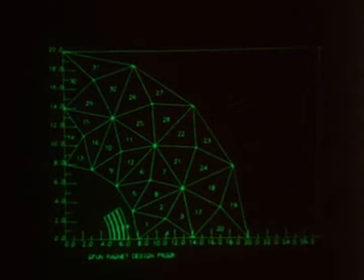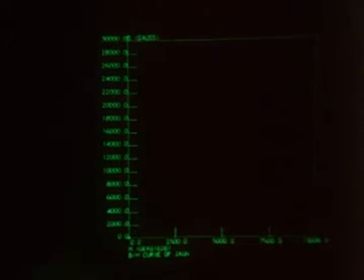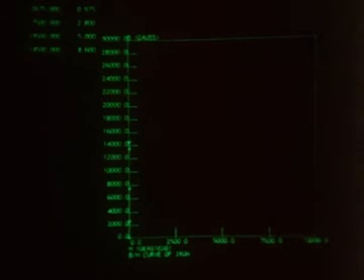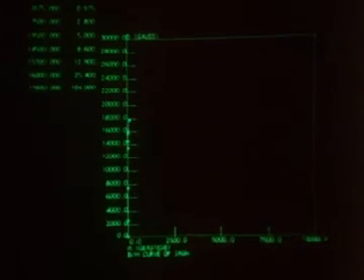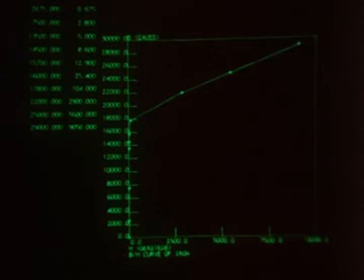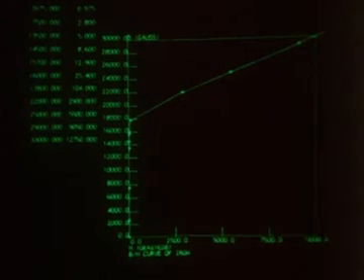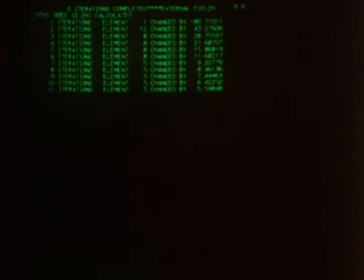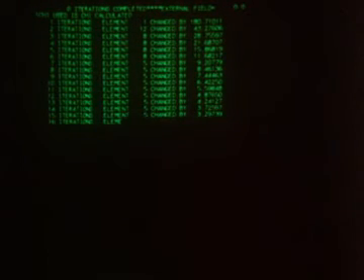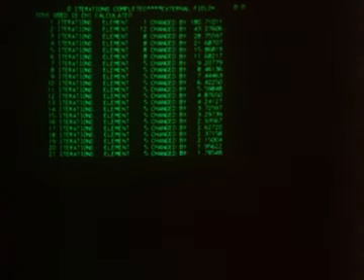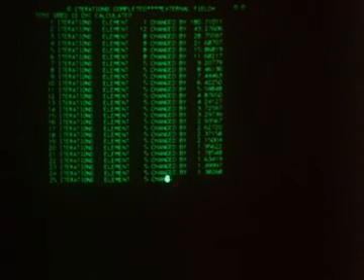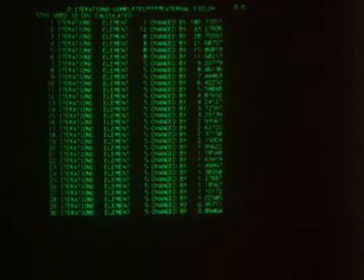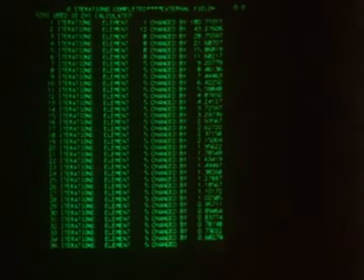Because iron is a non-linear magnetic material, the magnetic properties have to be specified. The necessary BH data is entered and plotted. Before the magnetic field can be displayed, the magnetization of the iron has to be computed. This process involves the solution of a non-linear integral equation. At the end of each iteration, the progress towards convergence is displayed so that the designer can halt the process when the problem has converged to some desired tolerance.